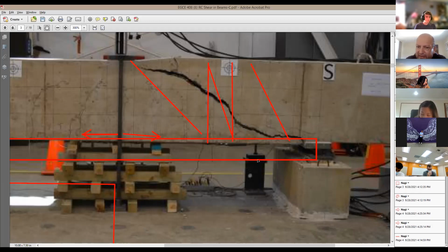So in a case like this, maybe 35 degrees or so, I can confirm that shear cracks will never happen unless the tie itself is going to fail. Why? Because the shear crack wants to happen at 45 degrees. And with the spacing between the ties equal to 1/2 of the beam depth as a maximum spacing, now you are preventing the shear cracks. You are postponing it, or pushing it. You're adding strength to the beam in shear.